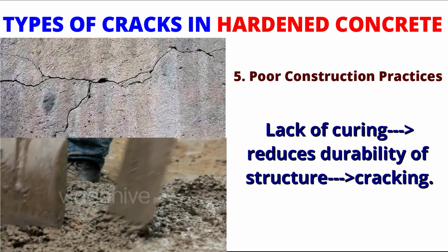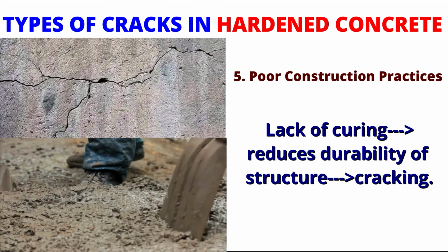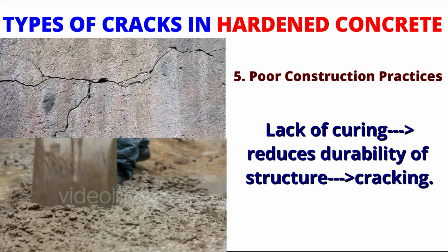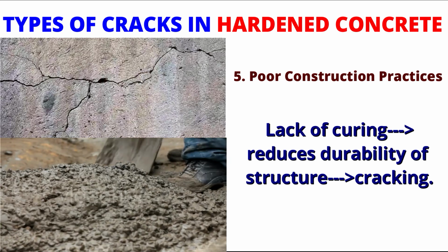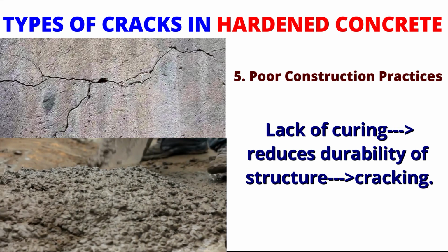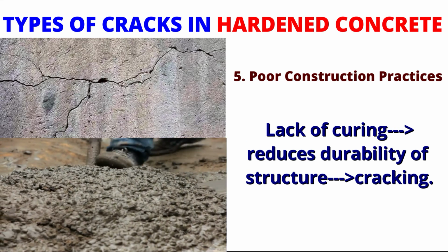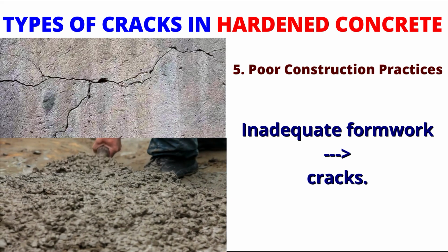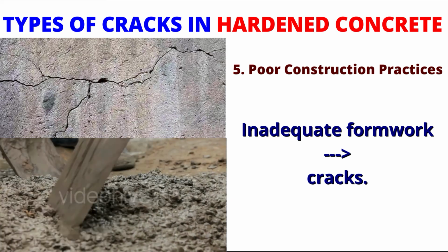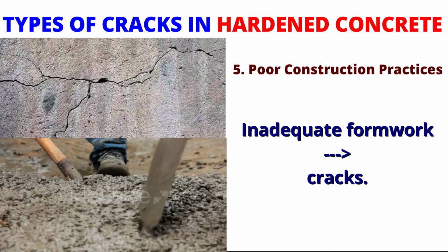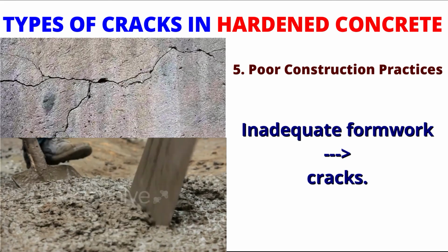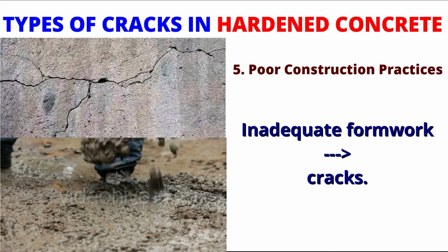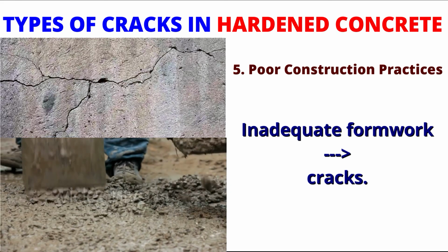Another common practice is lack of curing. The lack of curing will increase the degree of cracking within a concrete structure and reduces the durability of the structure. Another construction problem that may cause cracking is inadequate formwork and supports. So, to avoid poor construction problems, one must have good knowledge of the standard procedures and good code knowledge.